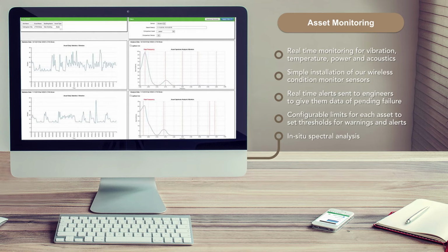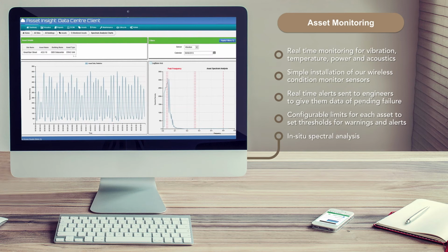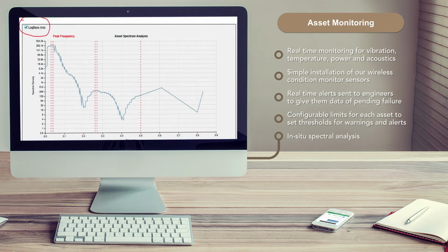Key frequency values can be attributed to a physical process, for example the rotation of a shaft, ball bearing or gears. By tracking key frequency points, the deterioration of key physical components of the asset can be monitored.